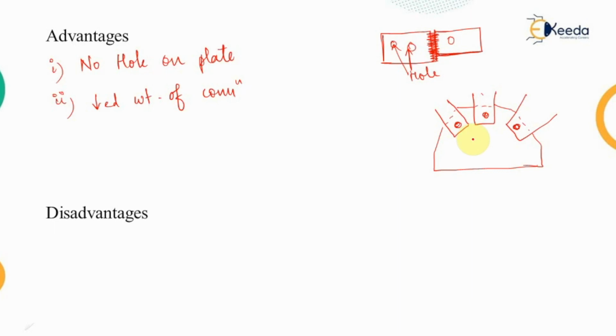Now in this case, when we are providing the welding, a bracket plate, a gusset plate, will be required here, but the size and shape of it will be reduced because now we are not providing holes in it, and therefore we need not maintain any gap between the different bolts. We will be simply welding them along the edges of the plates. That means this is to be done as the welding process. Therefore, since we are reducing the weight of the connection, it is an economical connection.